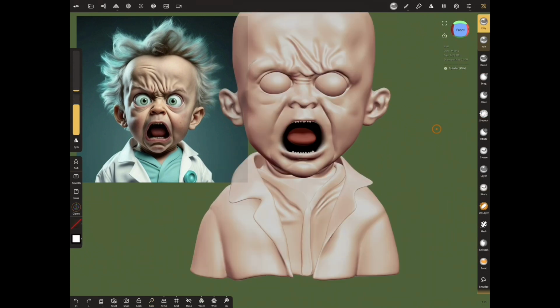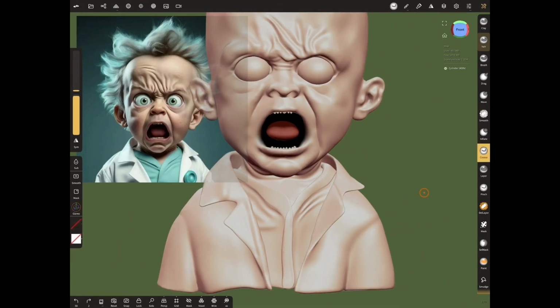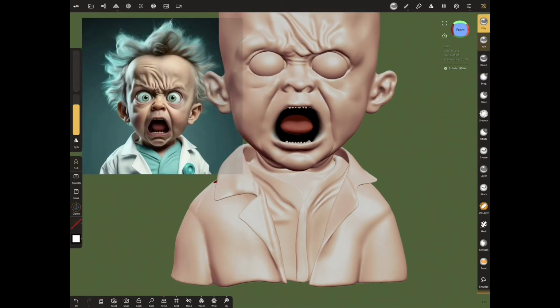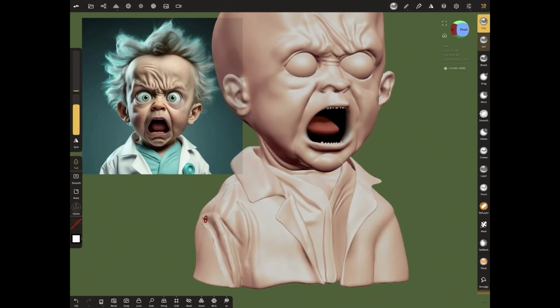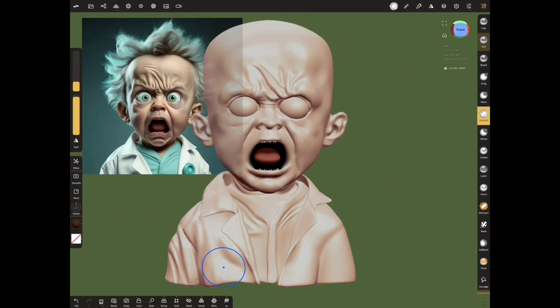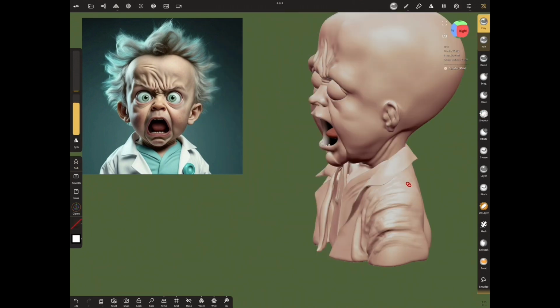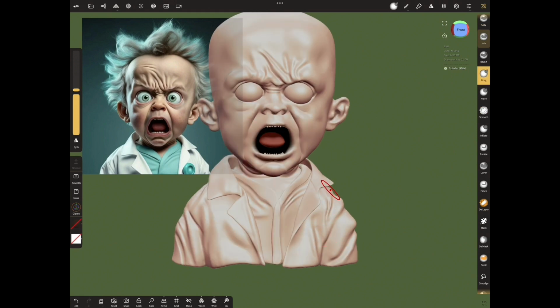Let's go through the fine-tuning of the merged apron. We can sharpen the edges of the collar using the pinch tool, and for the fold details on the apron, let's use the clay tool and clay sub. Bring the folds closer with the drag tool at low radius to make them more realistic. Since the back and sides of the arms are not visible, the details you make are left to your imagination. The more shapes you pour, the more details you can cover.